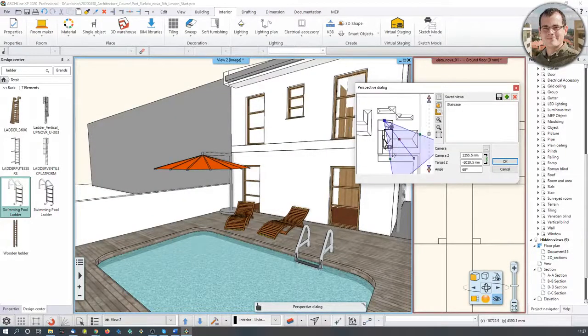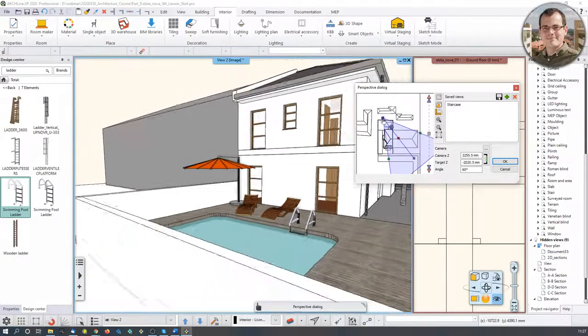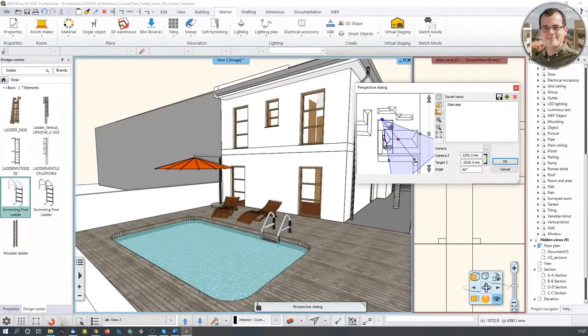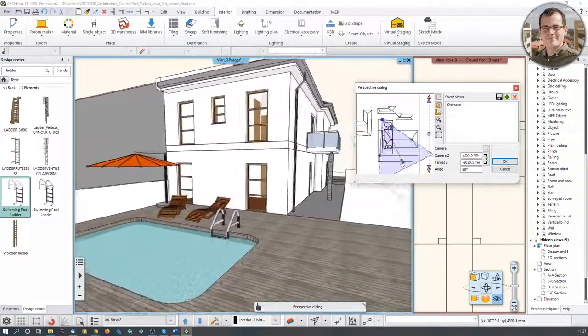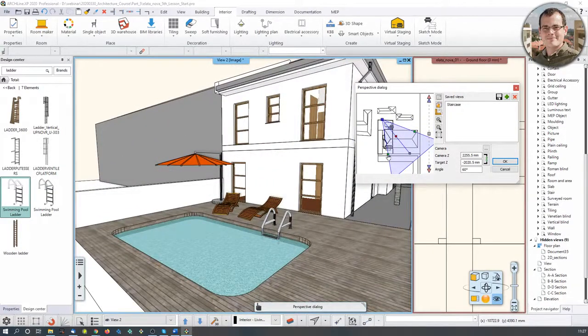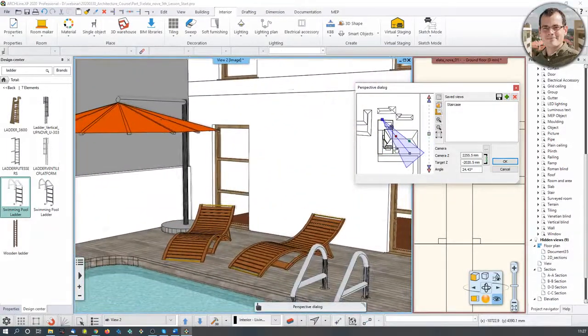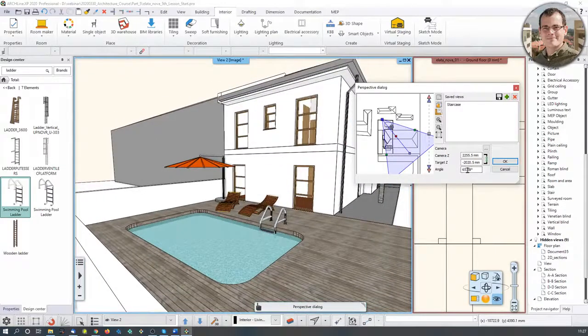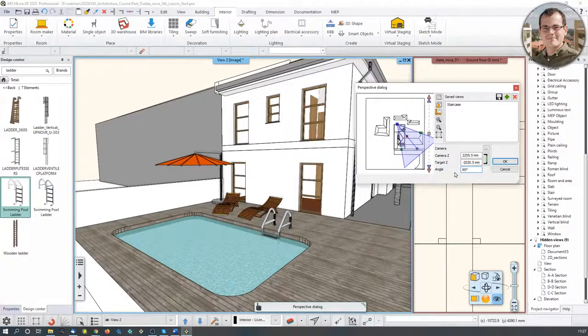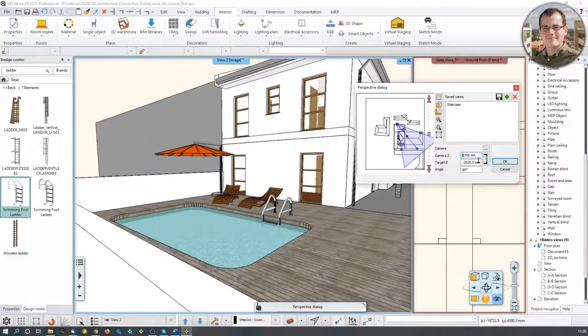The perspective is defined by where you are, which is the blue marker, where you're looking at, which is this purplish marker, so you can rotate that, and how wide you are seeing, which you can set up the way you want. But if you set it up too wide or too narrow, then your view would be a bit less natural. So it's good to keep this as 60 degrees. And also the height where you are looking from should be a human-sized sort of perspective. So it should be 1700 maybe, because that is, for example, my eye level. I'm approximately 1 meter 70.